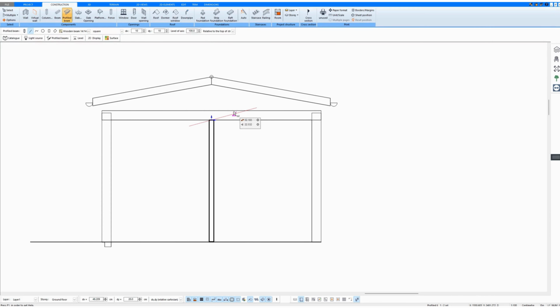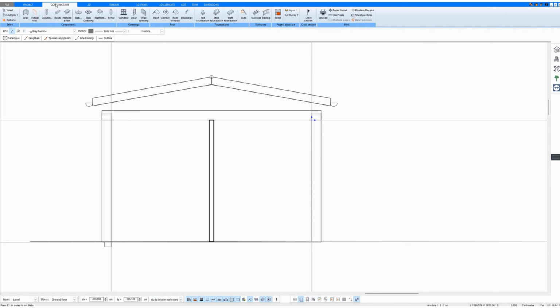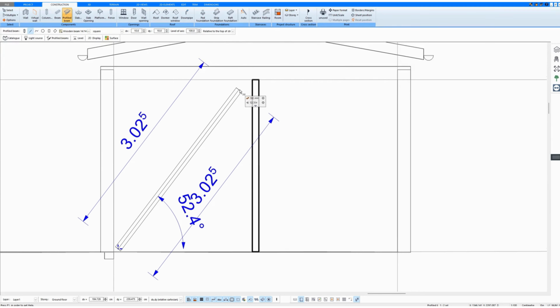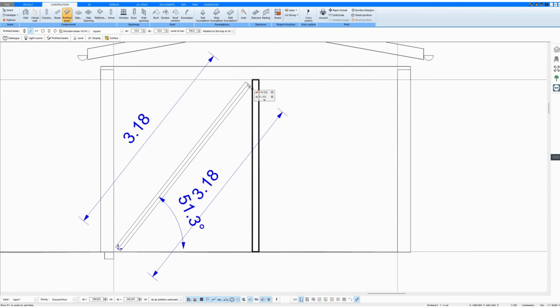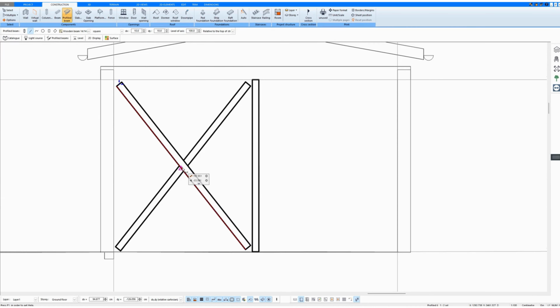Then, if I click on 2D elements and draw guides on the sides, I'll explain in a moment why I need it. Now I go back to construction mode and draw profile beams as a line again. And now I'm drawing my beams, but not to the end, not to the corner. You must always leave some more space, because these beams have to be connected at the end.